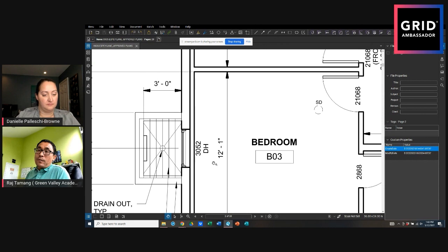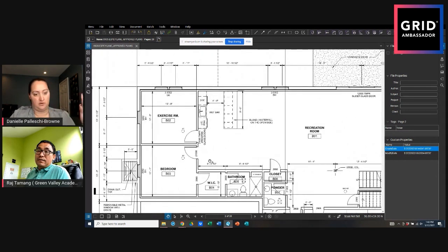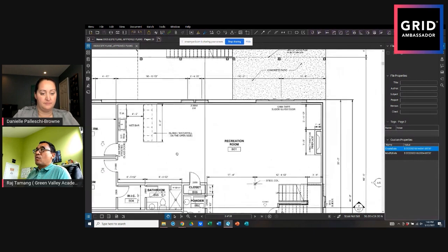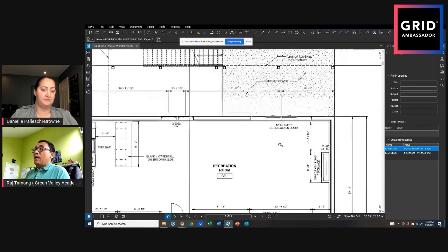So you try to avoid having tempered glass. But again, in places where, like you say, the window sill is less than 18 inches, by code you need it. Right? And that's just for safety, so it doesn't explode onto somebody if it gets hit or anything like that. Yeah. And like the door, of course, any glass door, French door, should also be tempered, because there is no window sill. It's right there on the ground.